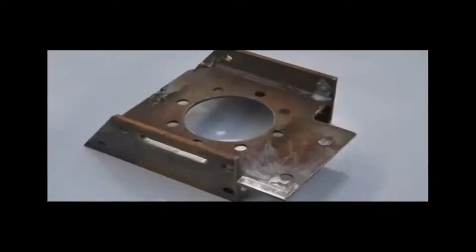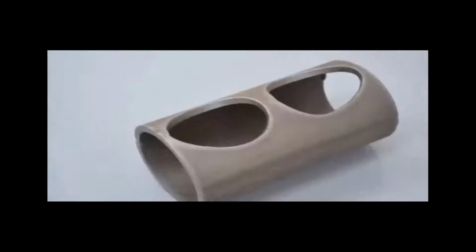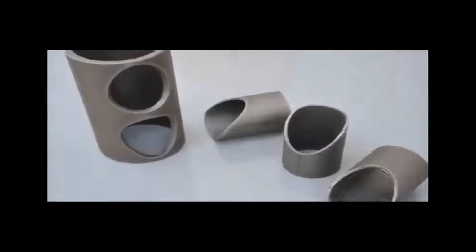As well as that, we have the three-dimensional coping. So you can see here the robot is cutting or coping these pieces as per the Tekla model again. All the instructions for slot holes, rat holes, notches on the side, all this information passed directly from Tekla. So any cuts or copes you put in Tekla are linked directly to this plasma cutting machine. And an example of the kind of finish or information that can be passed through.